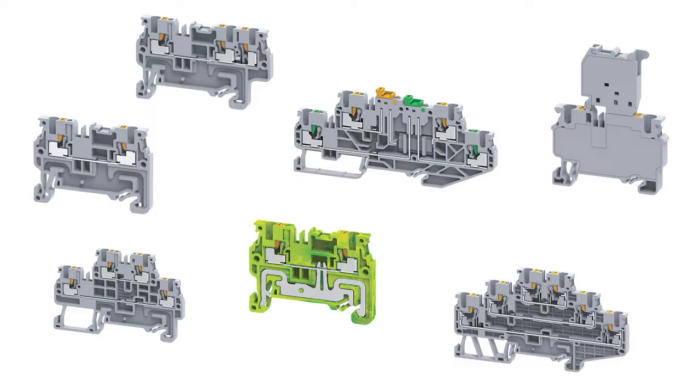All these usually come in different versions with grounding options. There are various fuse terminals available also, mainly for different fuse sizes and fuse types. These fuse terminal blocks also come in multi-level, multi-configuration options where we have additional feed-through terminals and grounding options. Or instead of the fuse terminal, we can have disconnect terminals as well.